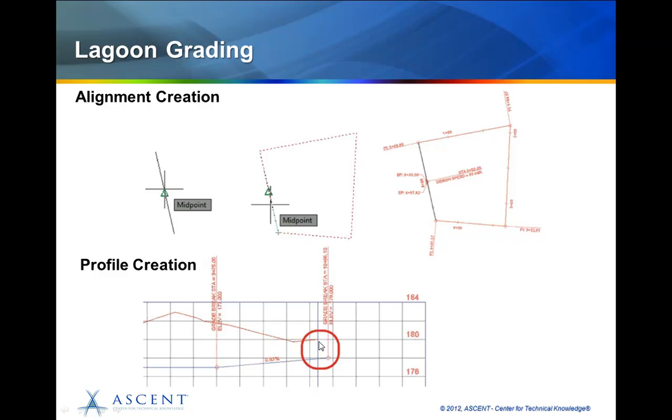I don't know how many of you work with corridors, but whenever you create a corridor and something funky happens and your contours suddenly go to elevation 0 at the end of your corridor, it's because your finish ground profile does not extend past the end of your alignment, and the software doesn't know how to handle that, so it just goes out to elevation 0. To avoid that, what I recommend is that you actually end the finish ground profile beyond the alignment, so that you don't have gaps and you end up with contours going to elevation 0.